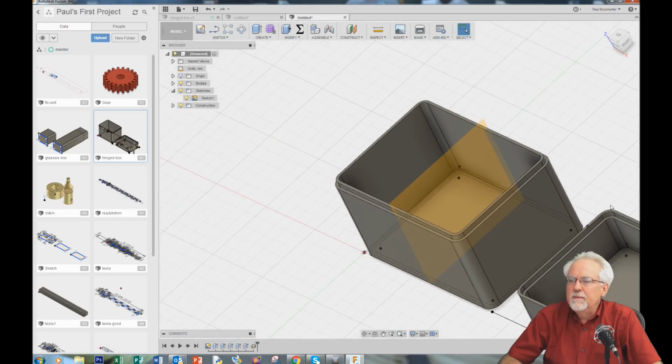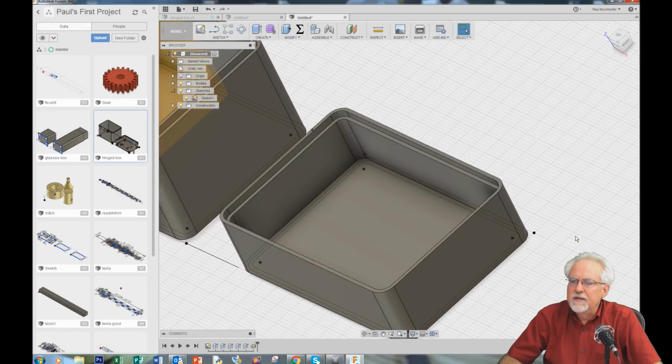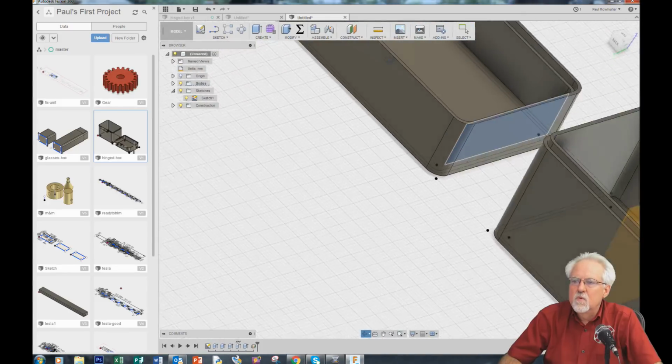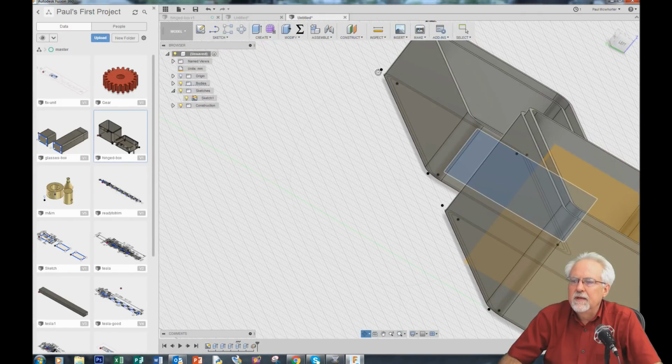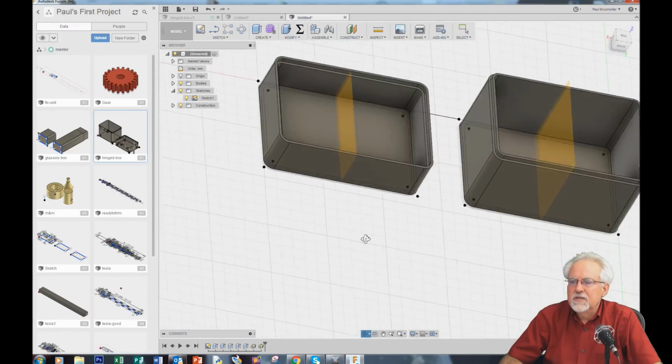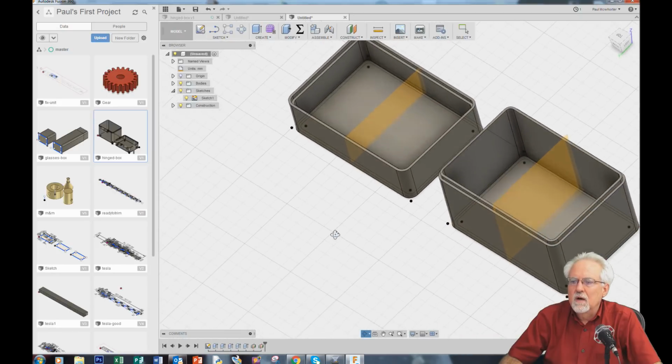Okay, and let me go ahead and put one on this other one so I get my plane set up. So what do I want? I want a mid plane, and I want it in the middle between this inside face. Very carefully get your rotate tool, rotate around where you can see that other plane. Right mouse click, say OK, because you want this to stay selected, and now select that one, and boom, look at that. I have my sketch planes now that I can draw on.